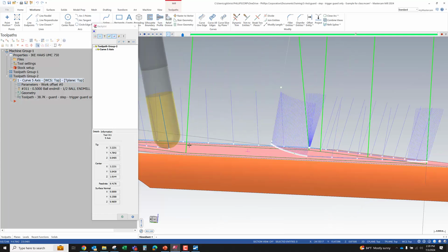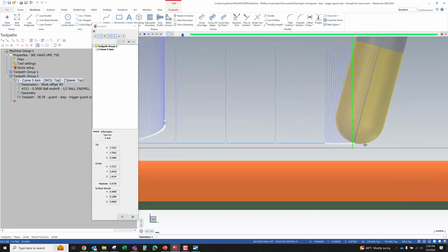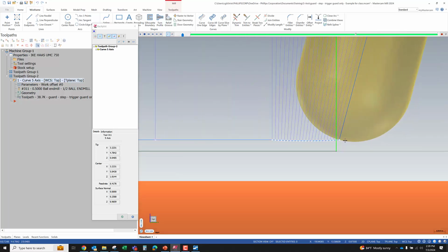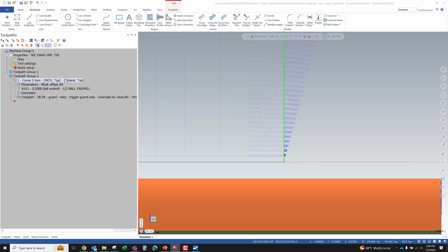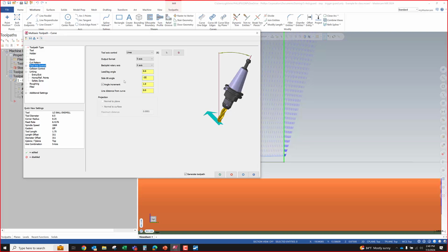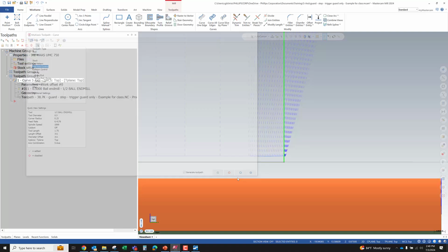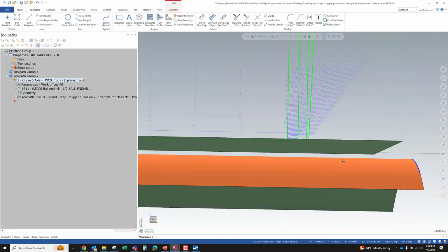And by doing that, we also wanted to rotate. Let me go right side. We wanted to rotate this 15 degrees, so now we're cutting here. More is better when we're talking about tilt. The further we can tilt on the ball, the better results we're going to get, provided it actually works and runs with any other geometry that we might have to avoid, etc. So if I said minus 35 degrees, this is going to be even sweeter. But you notice as it rotates, it has to compensate as well. So that can be an issue.